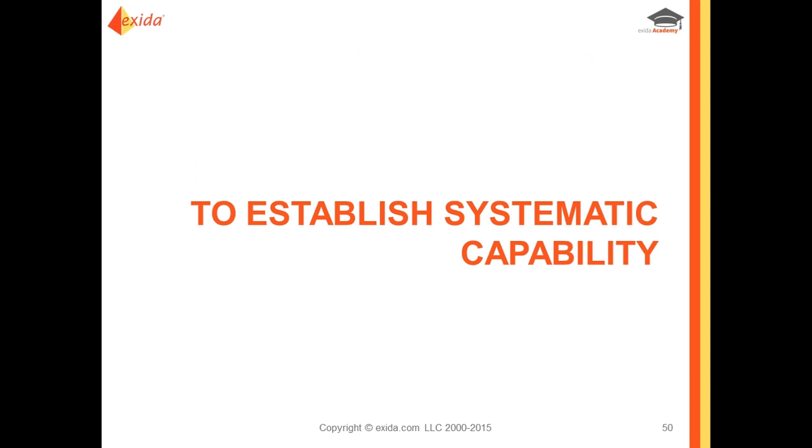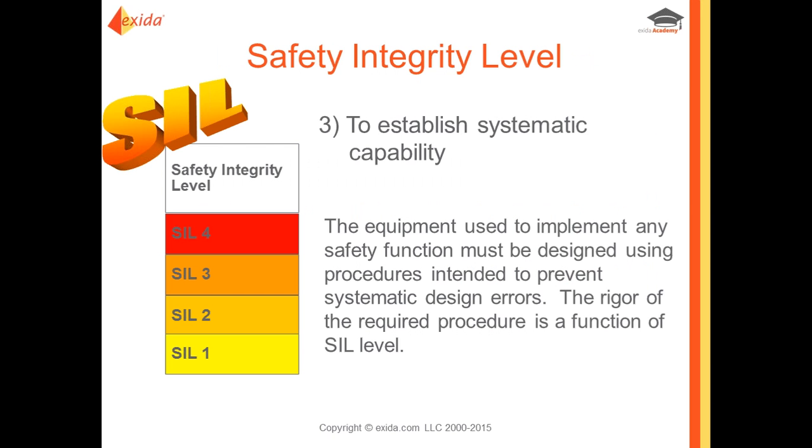And this is the type B safe failure fraction chart. As you can see, for type B, less than 60% safe failure fraction with no redundancy is just simply not allowed. So everything is shifted down and over one slot.